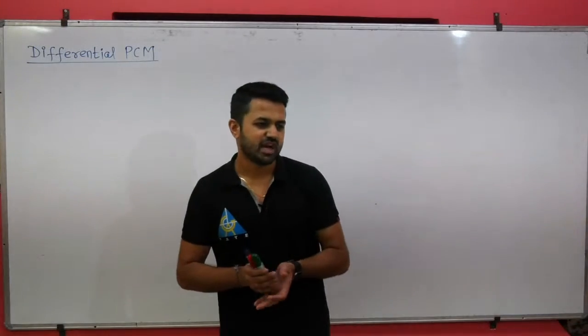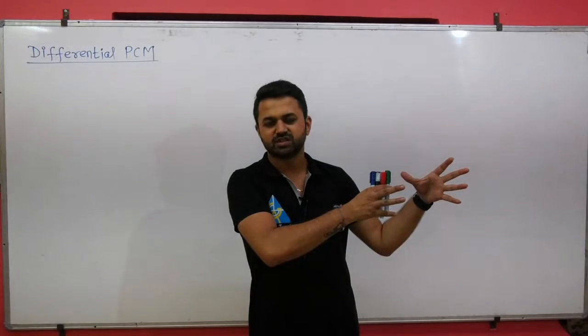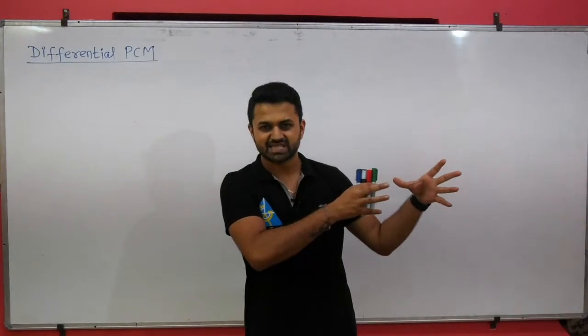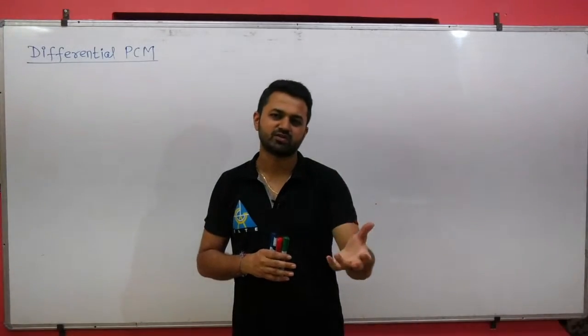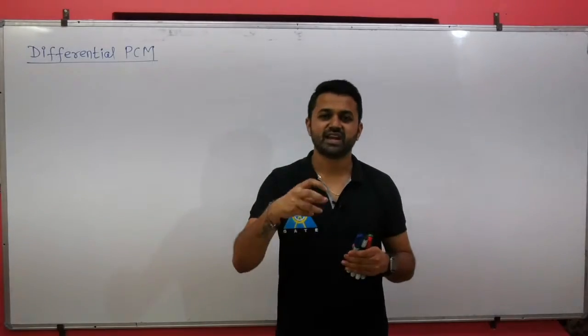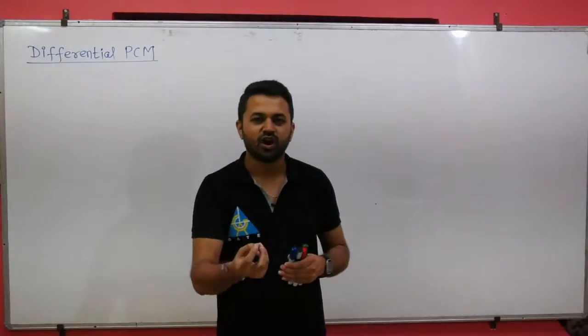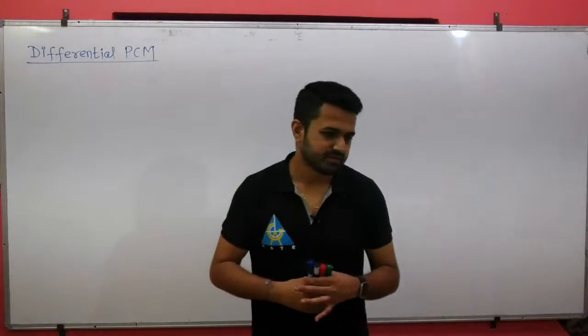Have you got this point? I had the past sample values, and according to those past sample values, I predicted that after 125 microsecond the sample should be 4.75. But when I took the sample, I got the sample value as 4.8 volt, then what will happen?